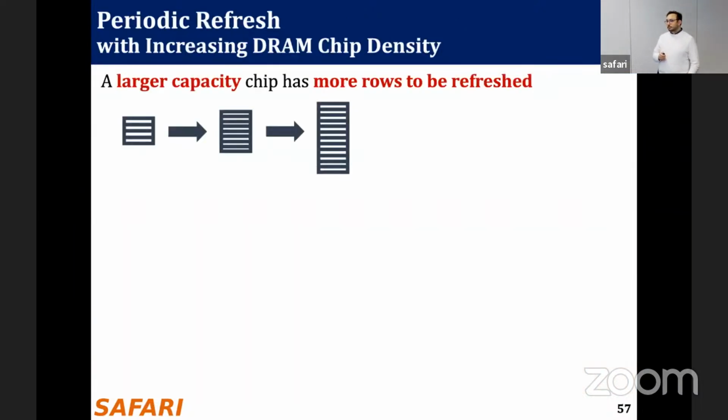I have a question. Yes. So is there any difference between DRAM refresh command and what we call preventive refresh? So I know that DRAM refresh command refreshes multiple rows at once, right? Yes. But is it the same as issuing act and precharge command, or do we know anything about that one?